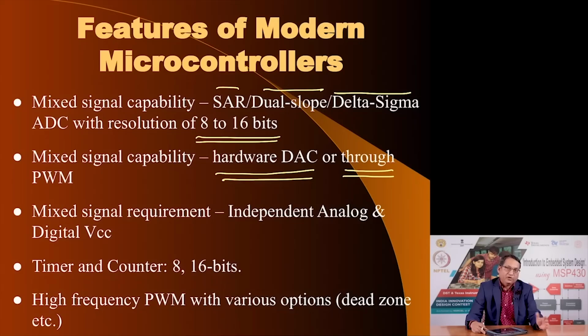dedicated to supply power to the digital part of the circuit and some pins dedicated to supply the voltage to the analog part of the circuit. This is because the voltage on the digital power supply pins often gets corrupted by the switching action inside a logic circuit, and this may leak into the analog circuit. So, the best way is to have independent power supply pins.